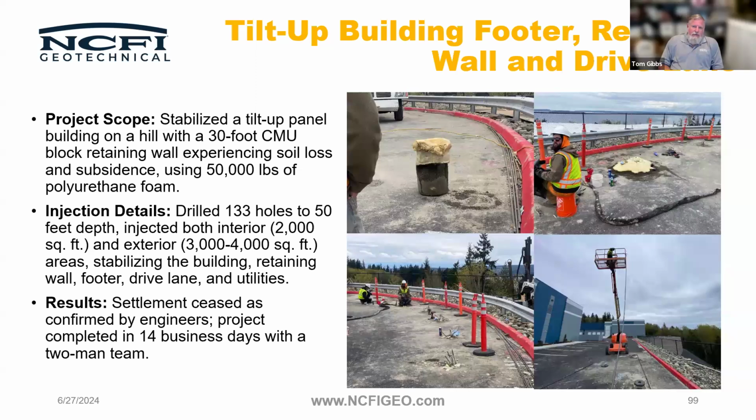You can have problems with freeze thaw cycles pushing the pipes back up if there's not enough overburden to hold them down. If it's in concrete, typically it's going to be locked in. I like to try and just take a crappy old drill bit and put it in hammer mode and push it down as far as I can get it to go down. That'll help keep it from being an issue.